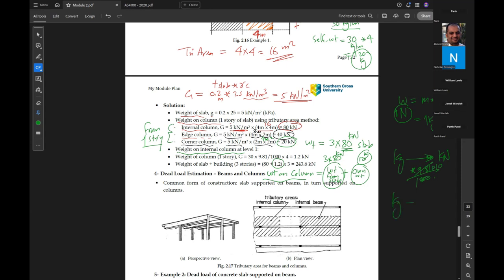So you multiply by 10 divided by 1,000, so it is like dividing by 100. So if the self weight is 120 kilograms, it is equal to 1.2 kilonewton, right? Is that logic?